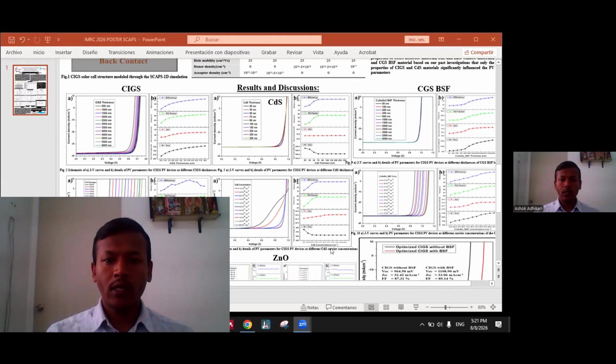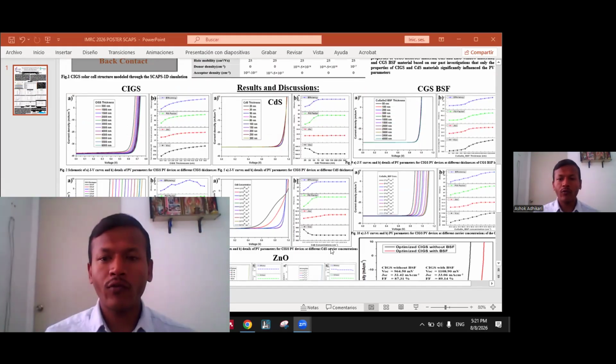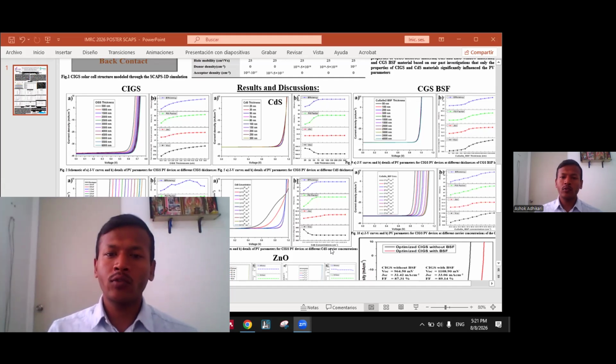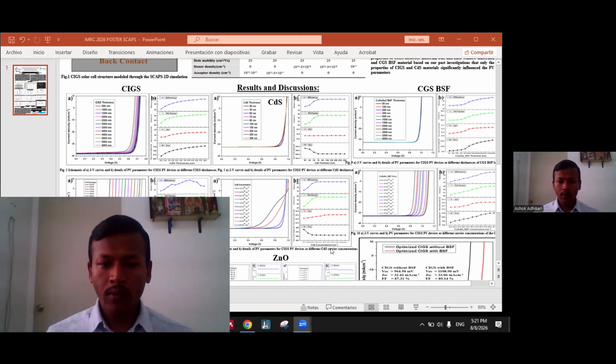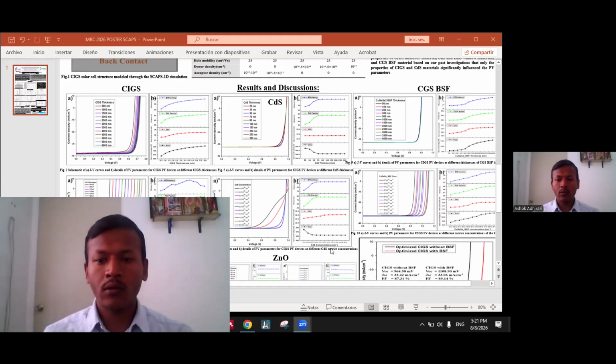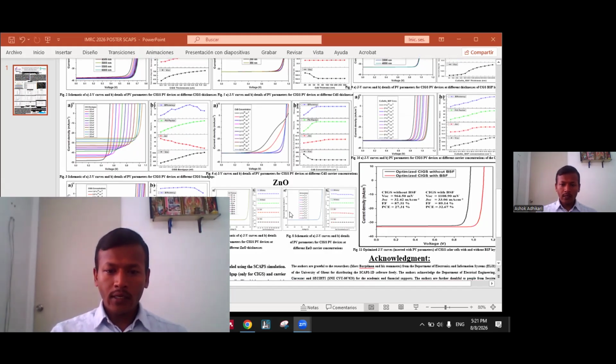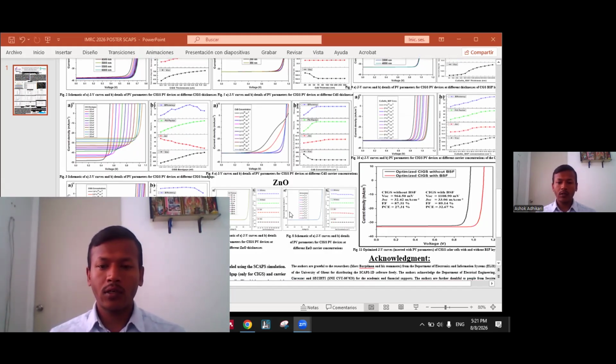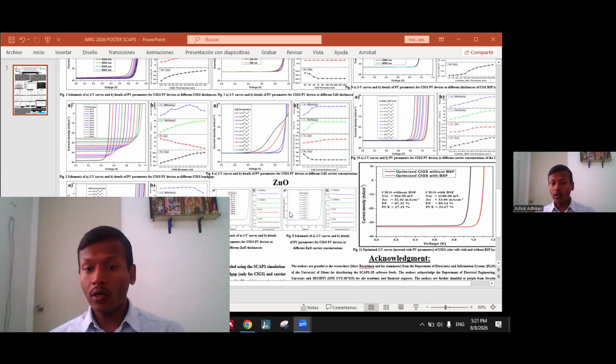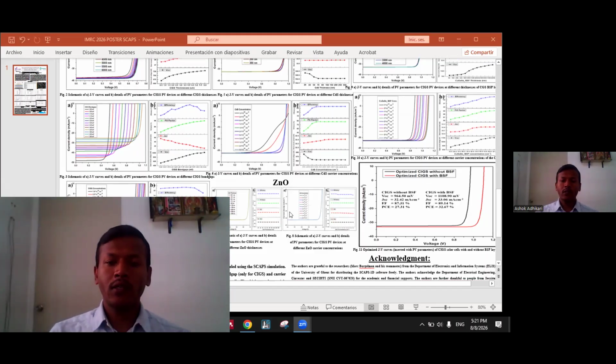So in this case, thickness and carrier concentration are primarily investigated. Around 50 to 100 nanometers is a suitable thickness for CdS, and similarly more than 10^17 is better for this layer. For the zinc oxide, if we change it, there are only very slight changes, since zinc oxide is far from the PN junction of the CdS and CIGS, so that's why this property is not showing any difference in the SCAPS simulation.